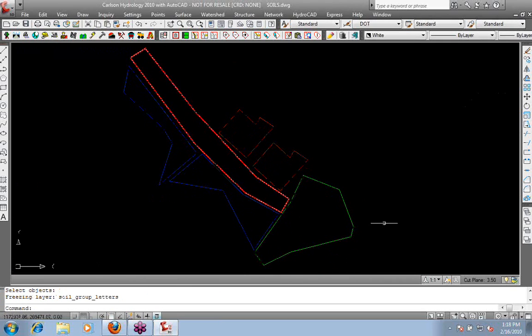This is what I wanted to show you: these are the ground covers defined on the specific layers that are in that list. The key to this is they're not labeled, so you don't need to label these, but they do have to be closed polylines. As opposed to the soils that do not, the ground covers do have to be closed polys. This was the second problem the person I was working with last week ran into.